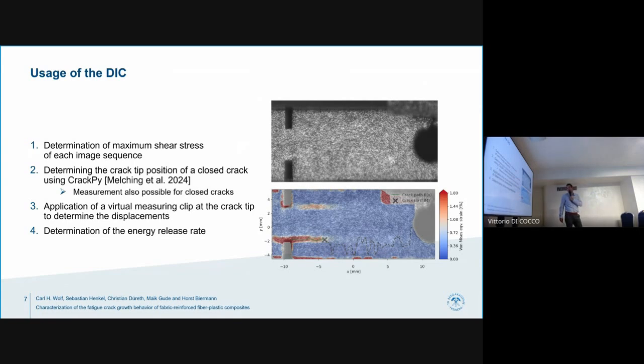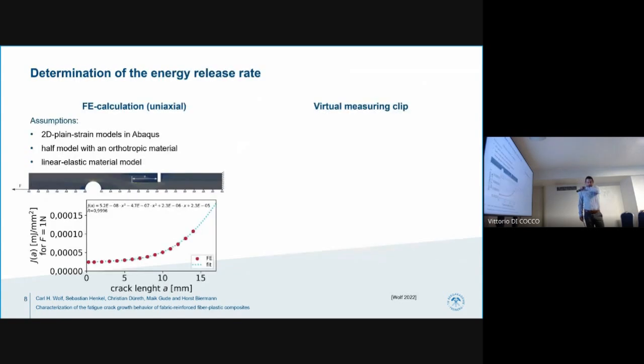I think David will explain the CrackPy later. And as we know the crack tip position, we applied a virtual measuring clip gauge and determined the displacement fields. And with this displacement field, we determined the energy release rate. I will explain later how it works.